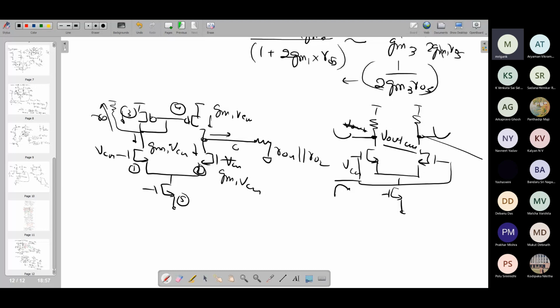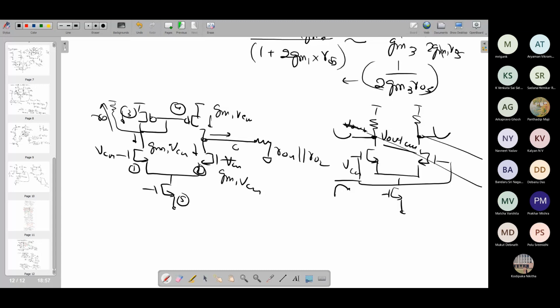In this case, if you take the signal differentially, that common mode signal anyway gets cancelled out. For a fully differential amplifier, if you take the signal fully differentially, the common mode signals cancel out fully, provided the circuits are exactly matched. Of course, if you have mismatches, we have seen that it will lead to common mode to differential conversion, and that will lead to corruption of signal. But if the transistors are matched, even if you have a common mode gain, you get it cancelled if you are taking the outputs differentially.